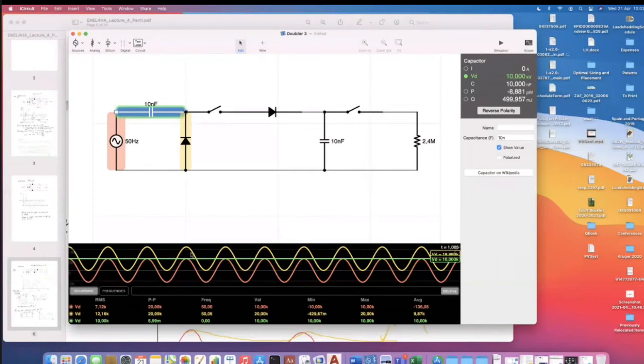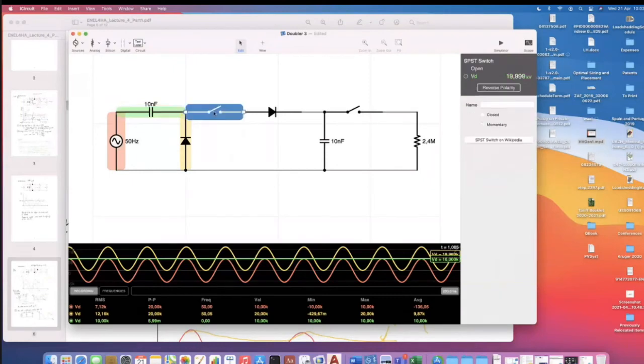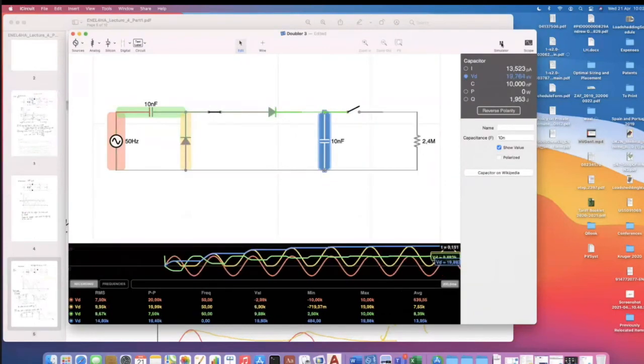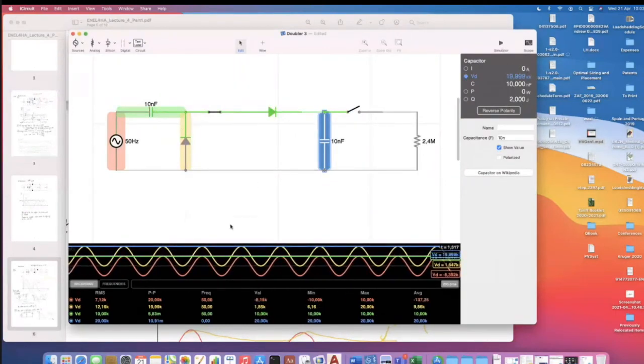That offset AC waveform is not actually useful to us yet. We're doing this system to make a DC voltage. So let's add a half-wave rectifier on top of that offset point. As soon as we add a half-wave rectifier, you can see the blue line there is now at 20 kV from your original peak. So we've doubled the original peak voltage.